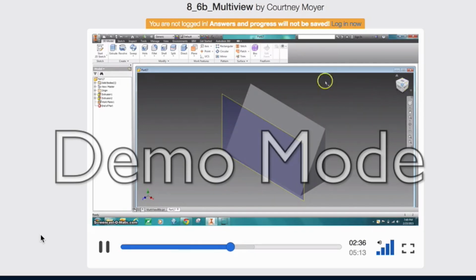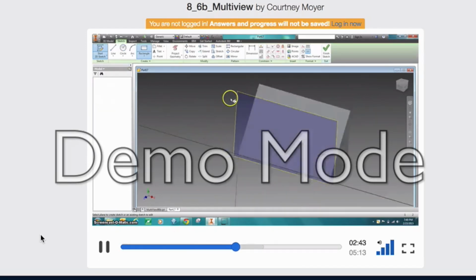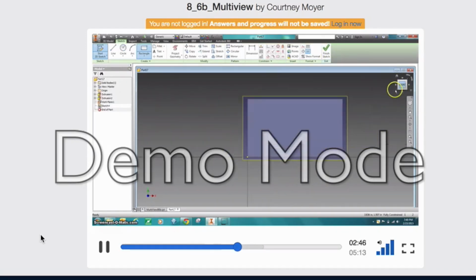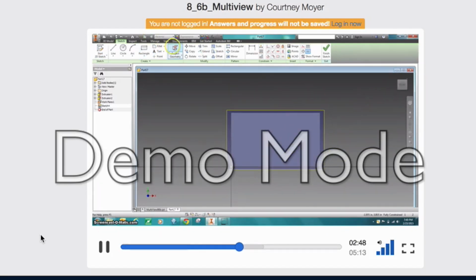Now what I can do with that is I can place a sketch on this plane. Okay. Now, as you can see, the plane, it even comes as work plane 1. It's actually bigger than the piece that I have. So now it's really important that I project that geometry. And from that projected geometry, I can create a rectangle approximately the size that I need.